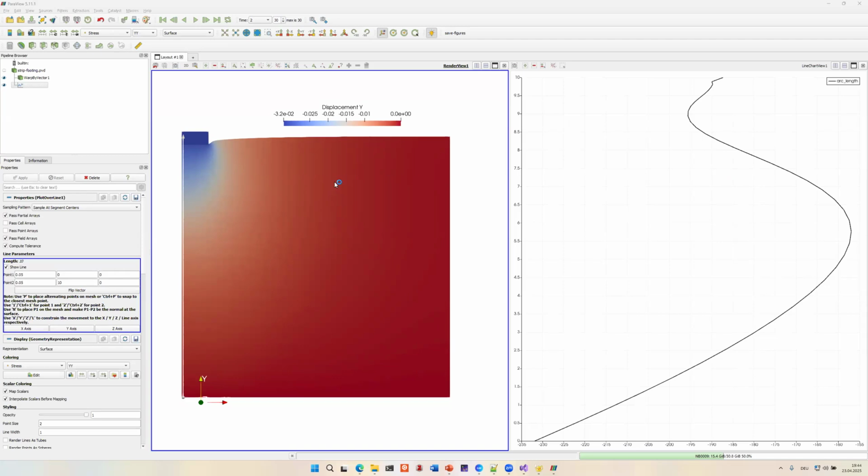Nonlinear geometries is the same as what Plaxis calls updated mesh. But Plaxis is not updating a mesh at all, right? This is just their name for nonlinear geometries, taking into account rotational components of the deformation. So we have that option to include nonlinear geometries for even larger deformations, right?